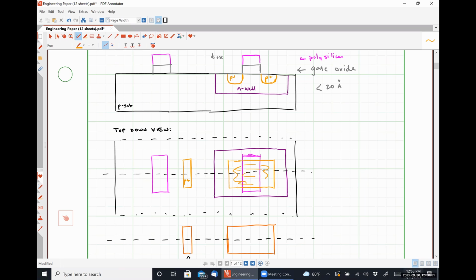The sheet resistance of metal is on the order of 1 ohm per square, maybe a little bit less, maybe a little bit more, depending on a couple of factors and which metal. So it's the best happy medium that we can get, and it also gives us the highest possible yield that we could ask for, okay?